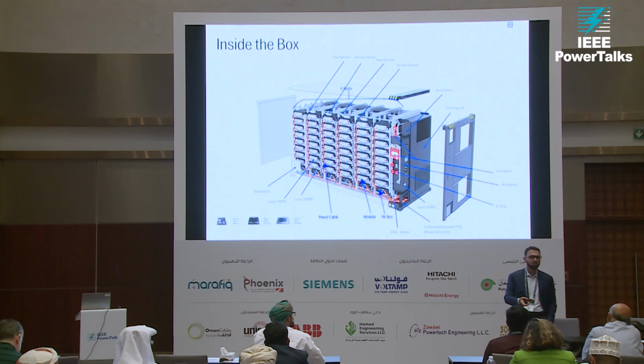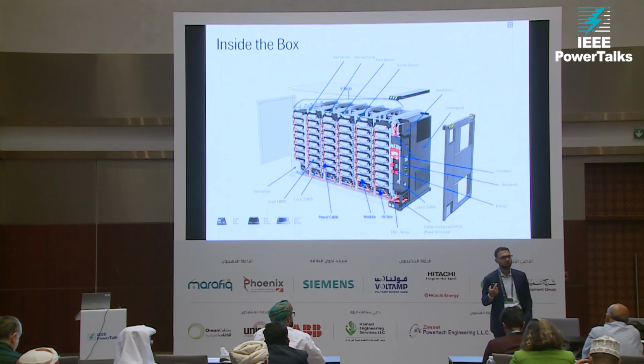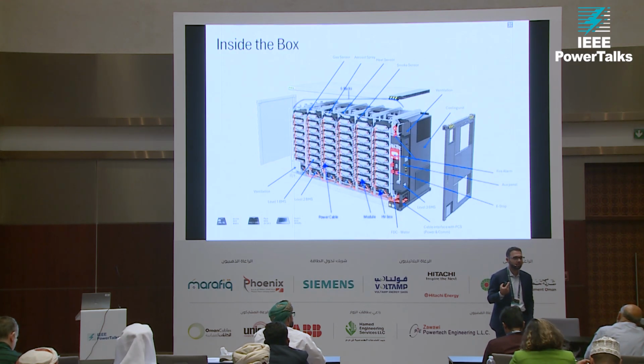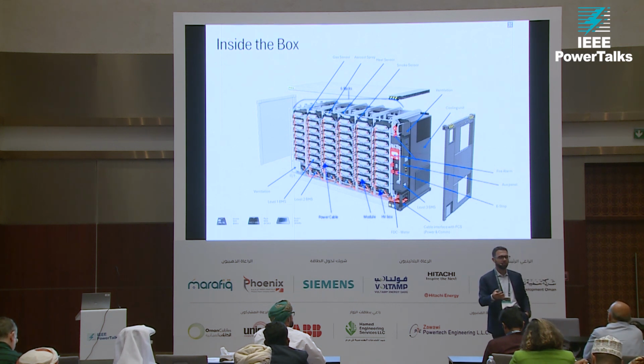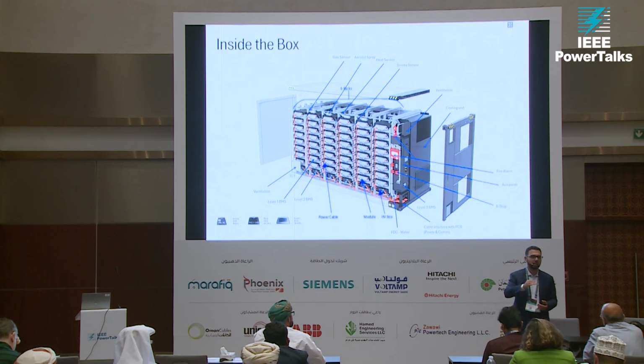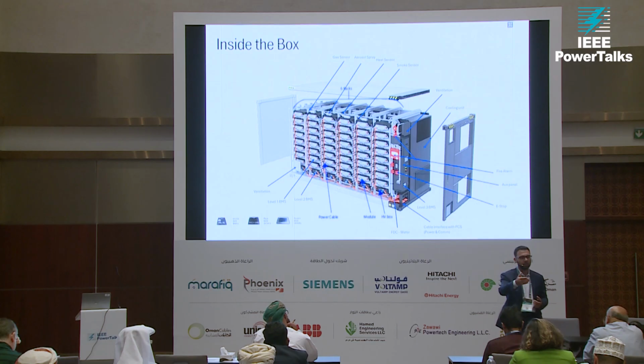So there are different methods, but from a battery standpoint, we actually classify them as, I believe, Class 1 in the US, which means they're low risk, because individual containers don't contain enough hydrogen to exceed limits to go to Class 2 or Class 3. So they're still individually looked at from a design standpoint.